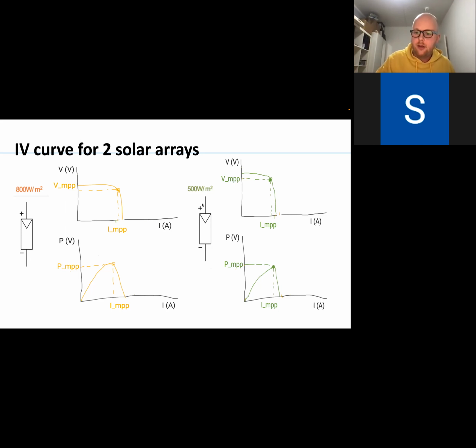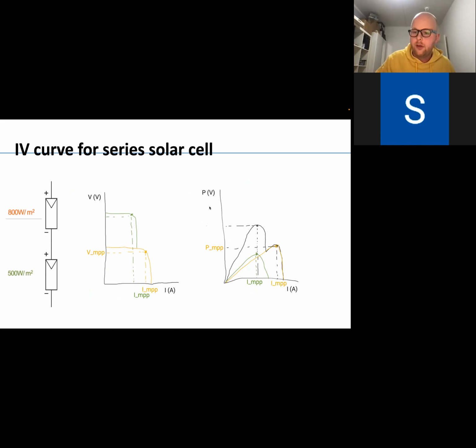On the right, I drew the maximum power versus current for that new IV curve graph that we get for this series combination. You can see that there are two little peaks on the mountain, of which one is higher than the other. Both of those peaks are local maximum power points, and the highest one is the global maximum power point.